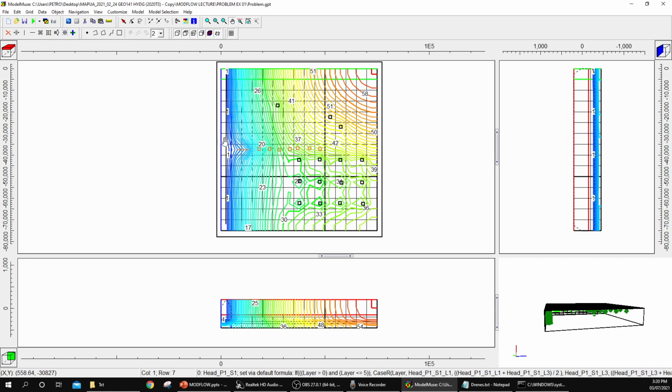So your external flow boundary is just forced to maintain a hydraulic head, a water table, of 0 meters elevation. So we specify that in the model, so it's just continuously consuming the water in the side. So it's pulling the water towards the side, and you get more or less the trend of the groundwater is down gradient towards this external boundary.